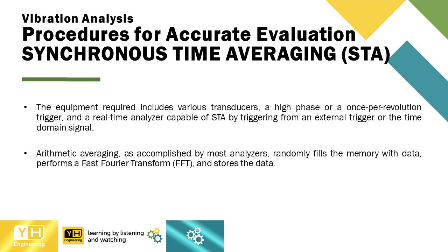The equipment required includes various transducers, a phase reference or a once per revolution trigger, and a real-time analyzer capable of synchronous time averaging, or STA, by triggering from an external trigger or the time domain signal.